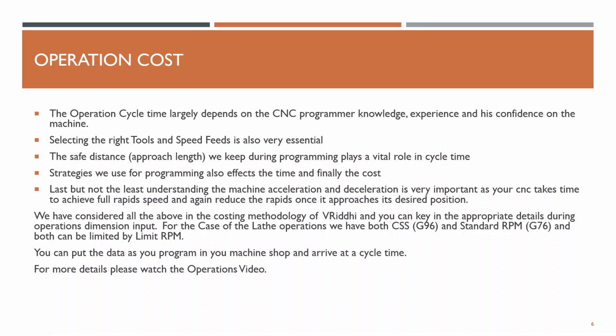Selection of the right tool, speed and feed is essential. Then the safe distance, the approach distance, is very, very essential. I have seen some programmers who keep a distance of 5 mm during drilling. I don't know why. But the confidence of the programmer in using the machine and in himself or herself is very, very essential. Third, a more important part is the strategies you are going to use for machining, and it really impacts your final costing. We will be doing some videos on operations, in which you could understand the difference of using the right kind of strategy.